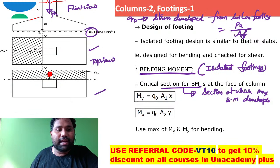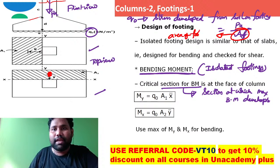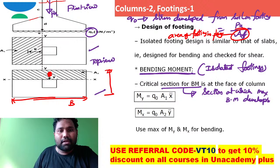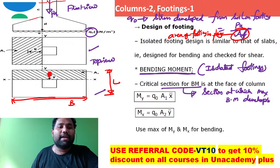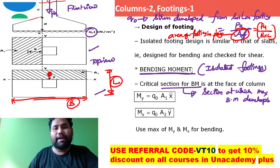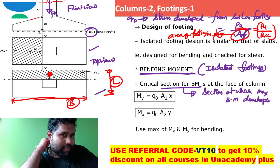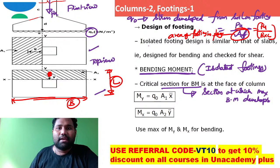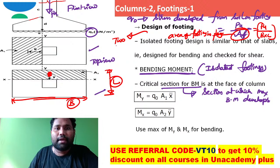AF stands for area of footing in plan. Generally in plan, this may be the width B and this may be L. So the area of footing in plan, from this figure, we can directly write as B into L. So we can write Pu by B into L. Now the question is, sir, how to work this out? This is a footing, just like a slab. This is a two-way slab having two-way bending action. The design of footing is like a two-way slab bending action directly.